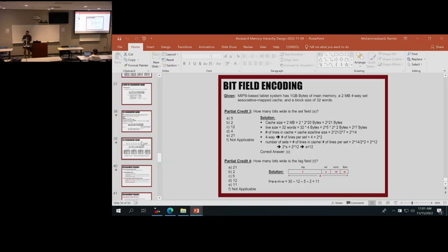Now no electrons go from one side to another side because they keep getting trapped at the capacitor. So you have to make sure that this capacitor is fully charged, and then you can transfer the information. The longer this path is, the more electrons are going to be trapped in this insulator, and the longer it's going to take to transfer this line from one side to another side. This is called parasitic capacitance. So these lines actually matter.